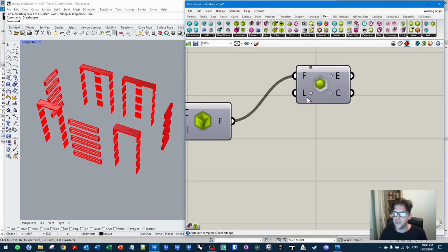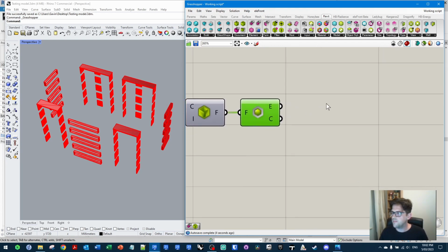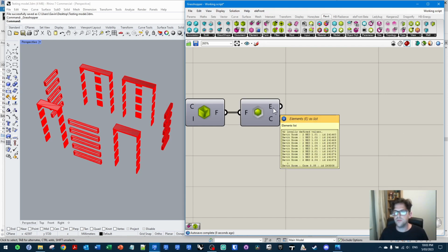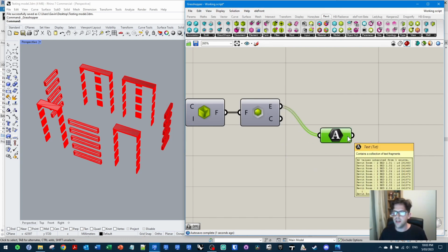And we're going to want to remove the L input, the limit, and just get as many rooms as we can. And at this point, we should have 42 rooms, and we just want the rooms called bed. Now, there's many ways to deal with the object at this point. We can get the parameter value of name. I just prefer typically to just turn this into text, which will usually contain both the room name and number.